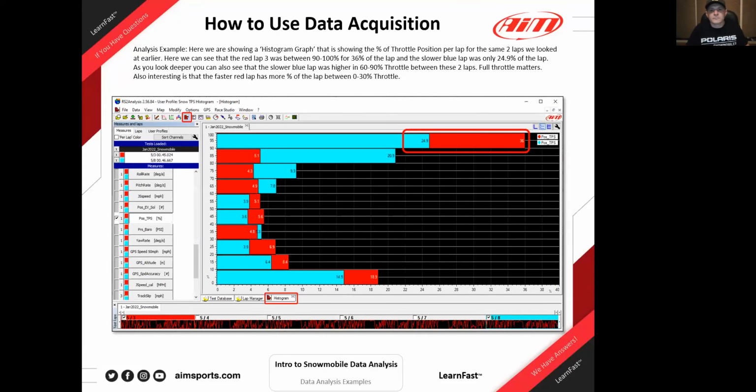One of the things that we might want to do, what's one good measure of if the snowmobile is working well and how the rider is doing with it, is how much time are they at different parts of their throttle position. The biggest one being how much percentage of the lap, we can do it either way, how much percentage of the lap are you at full throttle on these laps that are 1.6 seconds apart in lap time? And in this case, we have a function just for that. It's called a histogram button up here. I've circled it. Here's the tab when you open it. And you just turn on the throttle position and it automatically does the math for you.